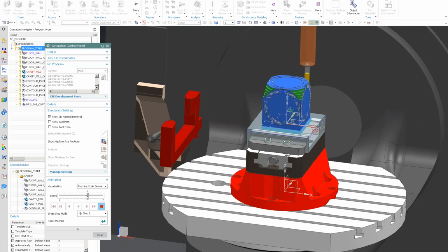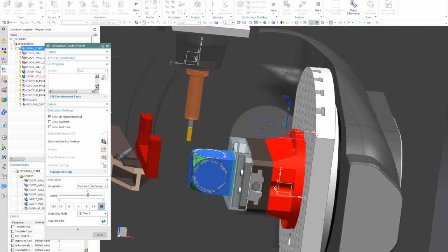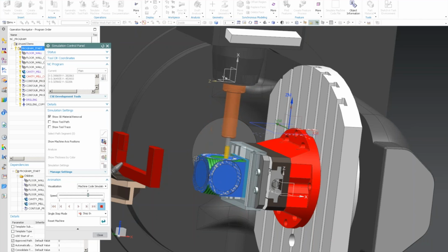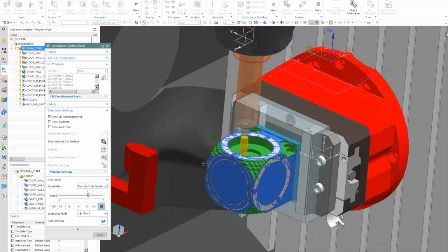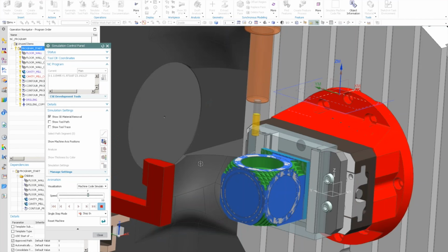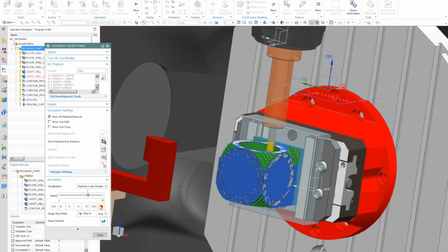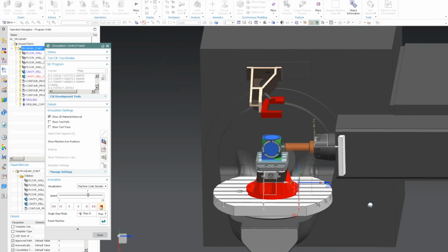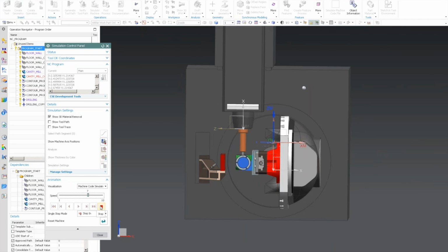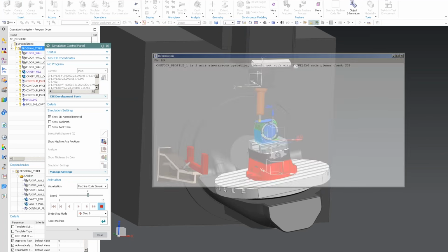We have high-speed toolpath types like trochoidal machining, similar to a volume mill. There are different names for it, but in NX we call it trochoidal, basically looping. I don't know if I selected it on this one. This is an overview, here's how NX works, here's how easy it is to create some multi-axis toolpaths, and we can simulate it for you and make sure that you're not colliding with your machine.